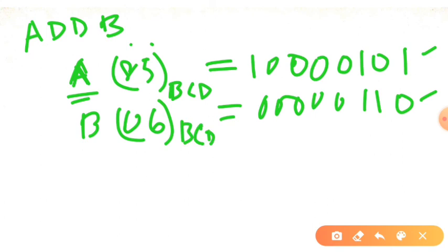Okay, so in a BCD number, obviously we vary from 0 to 9. It's a binary coded decimal number, so it's actually the decimal number. We do not have A, B, C, D, E and F, whereas in a hexadecimal number we vary the digits from 0 to F. So this is the main difference. So while representing the data in BCD, obviously we can expect that none of the lower order 4 bits or higher order 4 bits of any of these registers are greater than 9, because we have considered them binary coded decimal digits.